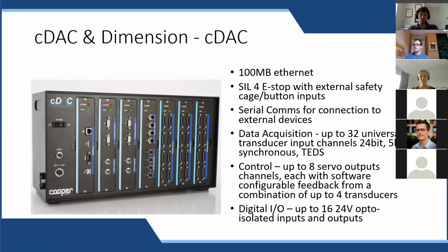We can have up to 8 servo outputs as well, so we can control up to 8 actuators all synchronously. Any of the channels that we use for data acquisition can be used for feedback, and we can have a combination of up to 4 of those to feed back to any channel.